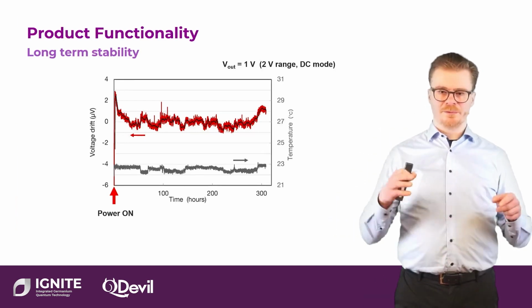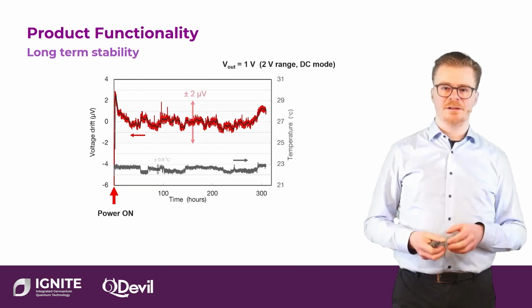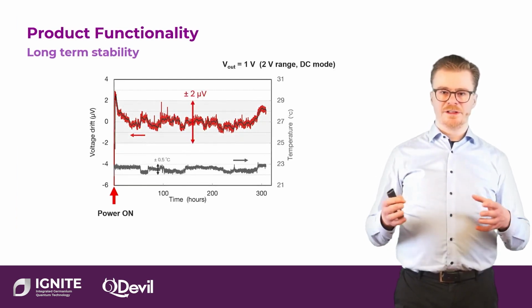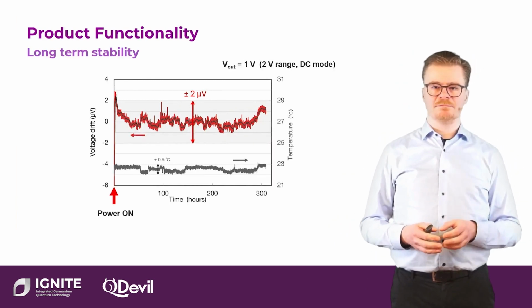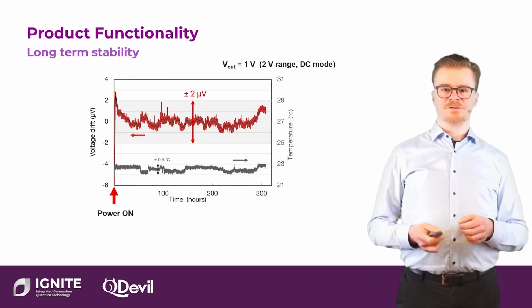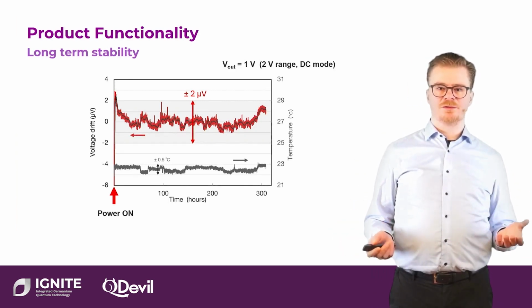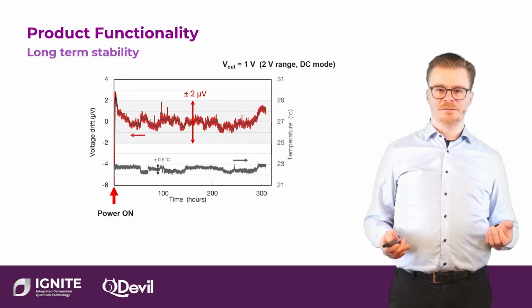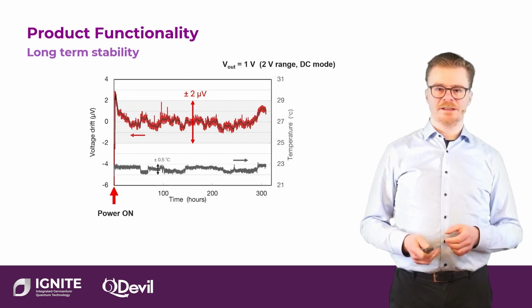At the lower point, you see that it was placed in a lab where the temperature fluctuates roughly half a degree, and that means it's actually staying voltage stable over several weeks to a few microvolts. So an instrument that can do precision control to a few microvolt precision, and at the same time with microsecond resolution.